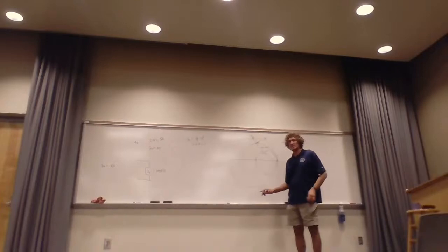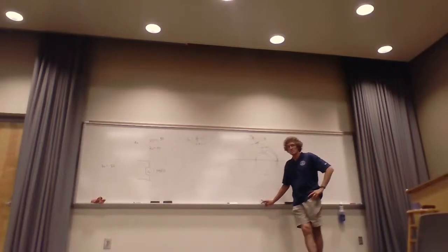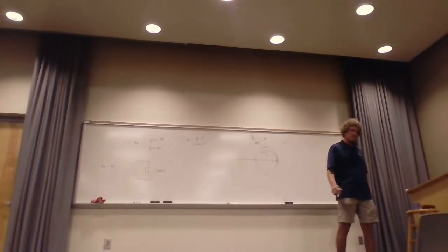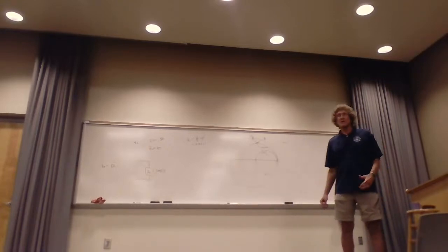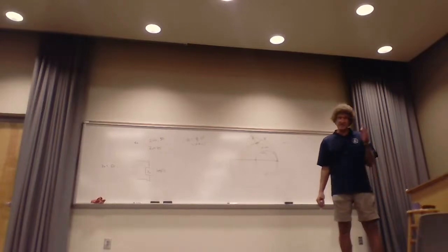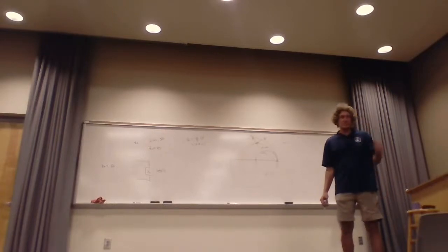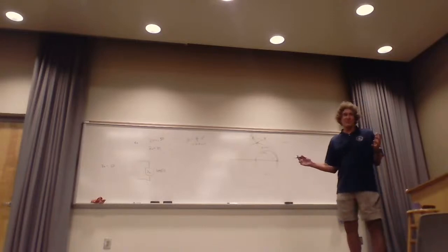And what else does he ask in this one? For design of the L section matching network, just like load impedance lines like this. What does he say about it? Does he want an inductor in series? The real thing is, if you want an inductor in series, that's the key. It asks for all 4 processes. Okay, we're going to do 1 of 4.